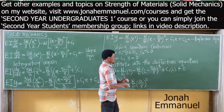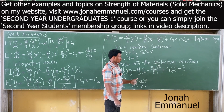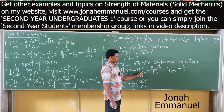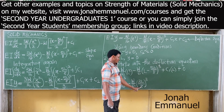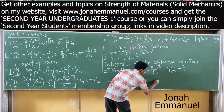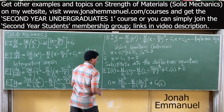So when you do L minus 5L over 8, what to do is simple. The coefficient for the first L is 1. For the other L it is 5 over 8. So if you punch 1 minus 5 over 8, you get 3 over 8. Attach the L, then cube. Plus C1L. All right, let's expand this.